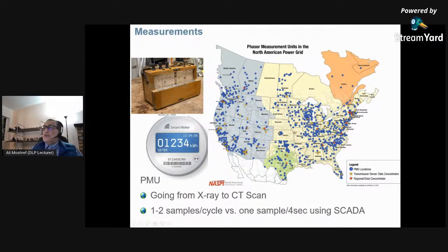We have also gone through something very important, in my opinion, that was not available in my time, when I started engineering. That is called the phasor measurement unit. A phasor measurement unit measures, like any other meter, quantities like voltage, current, power, and phase angle, and it can communicate through satellite or other communication with other measurement devices, and create a synchronized reference for all the measurements around the network, so that I can know the relative angle between Ankara and, let's say, another location. Then I can use that voltage angle difference for decision making.